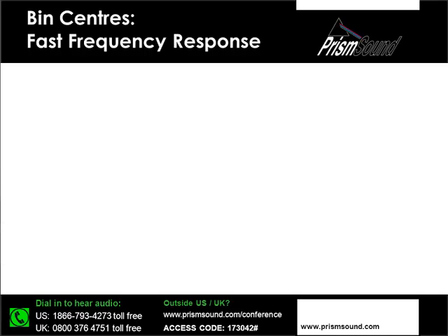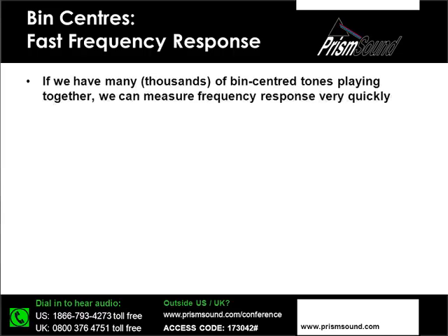And this now leads us on to something rather interesting. What we find is that we can actually use an FFT process, which is relatively fast, to perform something quite sophisticated like a frequency response measurement that would traditionally have required the use of a stepped sinusoidal sweep, which is relatively time consuming.